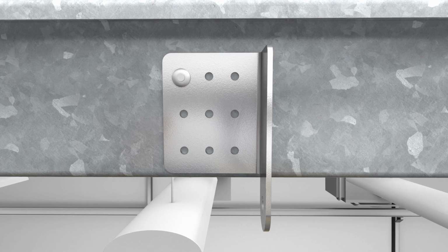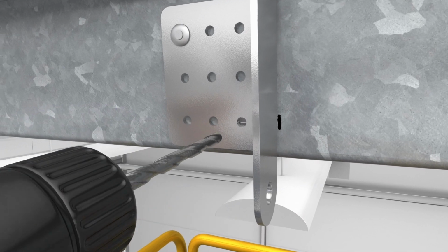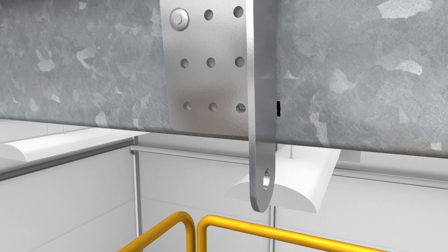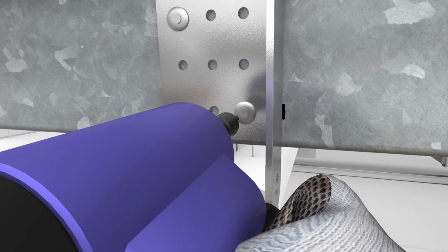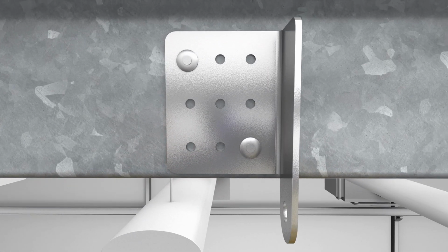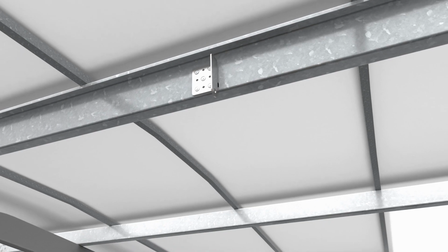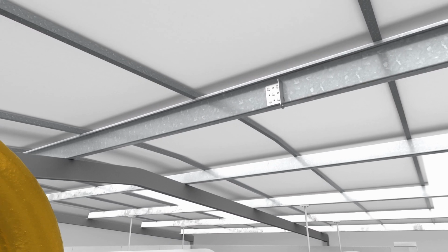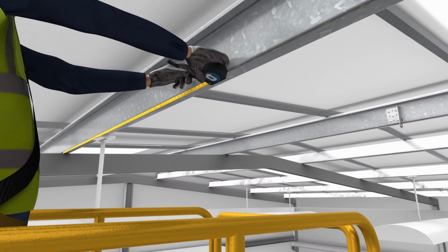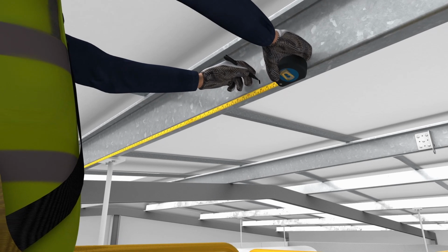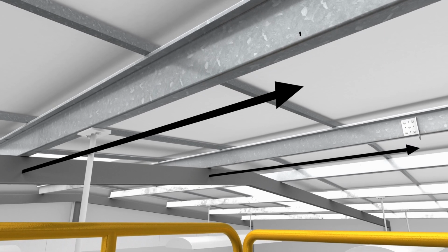Using the parallel purlin bracket holes as a template, drill through the diagonally opposing corner fixing hole, ensuring not to move the bracket. Insert and deploy a second rivet. Once the opposing corners are riveted, inadvertent orientation of the parallel purlin bracket will be eliminated. Using the datum in conjunction with the rail trajectory, establish the position for the opposing extremity parallel purlin bracket. Unless the datum is staggered, the distance from the datum to the opposing extremity parallel purlin bracket will be equal to that of the first.